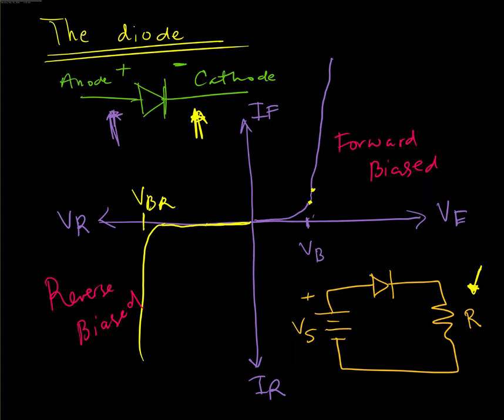You're going to get several different points along this graph, and you'll see how much this diode voltage changes, and you should see that it's quite close to this forward bias voltage. As this resistance goes down, the current in the circuit goes up, and if I raise this resistance, then the current goes down.